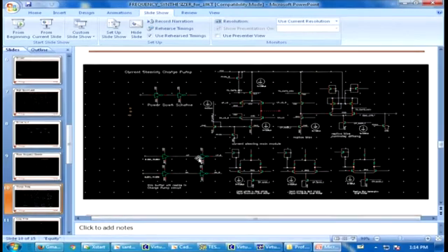Higher speed why? Because to go from 0.6 to 1.2 volt, you have to take less time, correct? Rather than 0 to 1.2. So that's why it is a much faster logic. This is a charge pump circuit. Actually, it might not be clearly visible, but the charge pump circuit will look like this way.